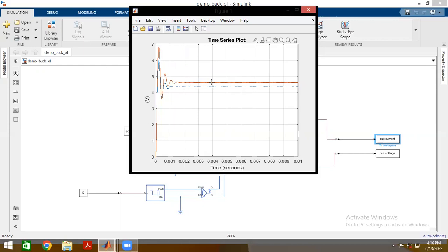That's almost 160% overshoot, and that could be catastrophic to a sensitive load. If you're going to have motorized loads or something like that, then they're not going to run as efficiently during this transient phase, because your motor speed, in most cases, will rely on your supply voltage.